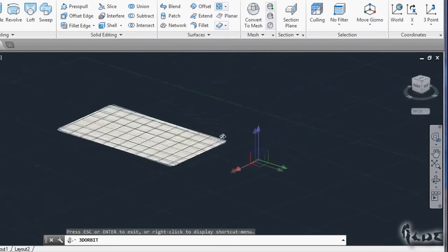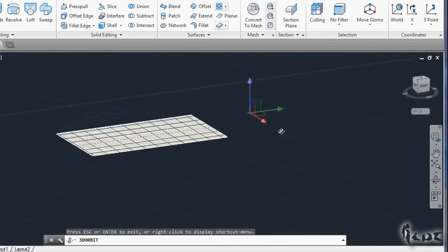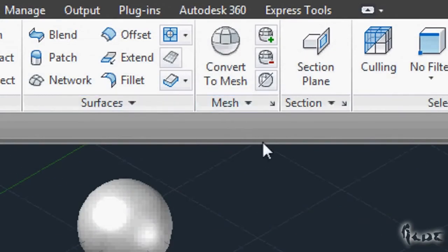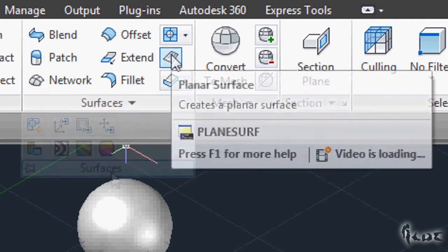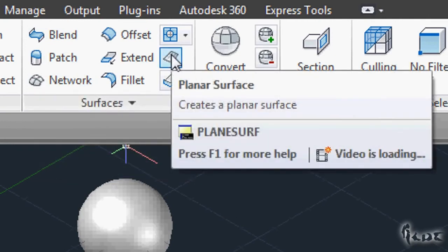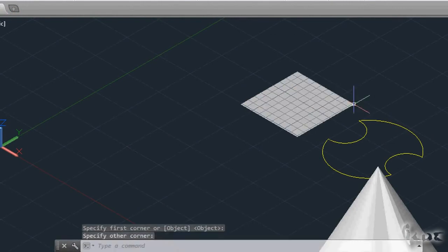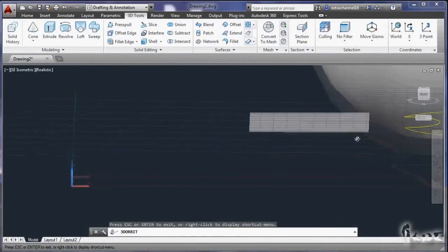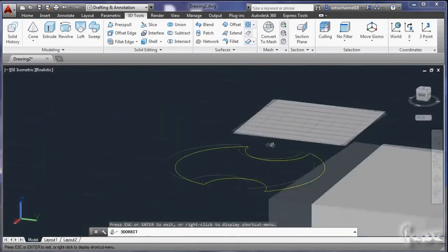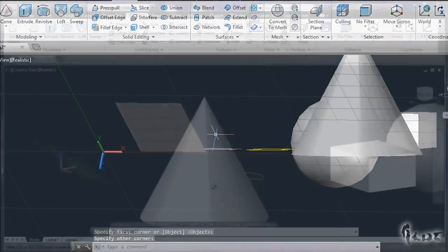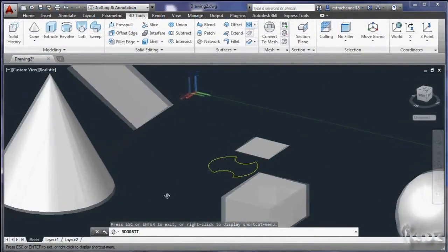In 3D you have also the surfaces. These are 2D objects but treated and modifiable like 3D objects. In 3D Tools, the Surfaces section has all for this. Click on the second icon on the right to draw a plane surface. And remember that such will be always parallel with the XY 2D area. You will need to rotate the Cartesian system to draw with different angles. Then you can use the other buttons to edit them properly.